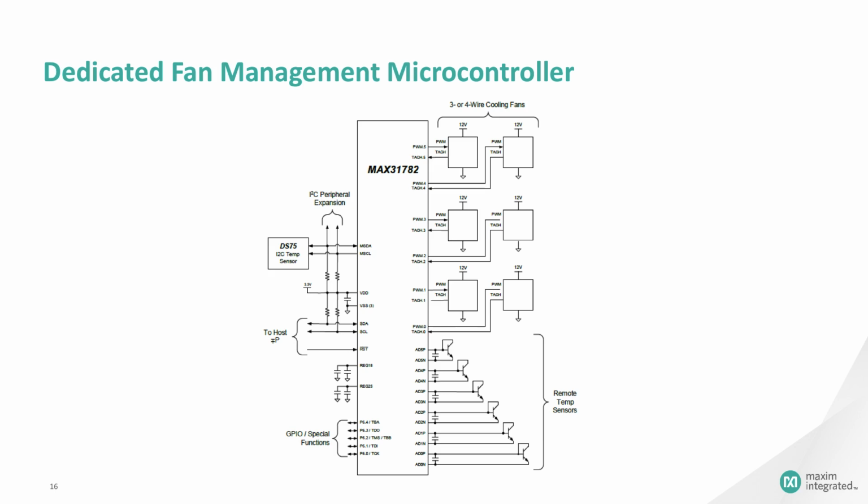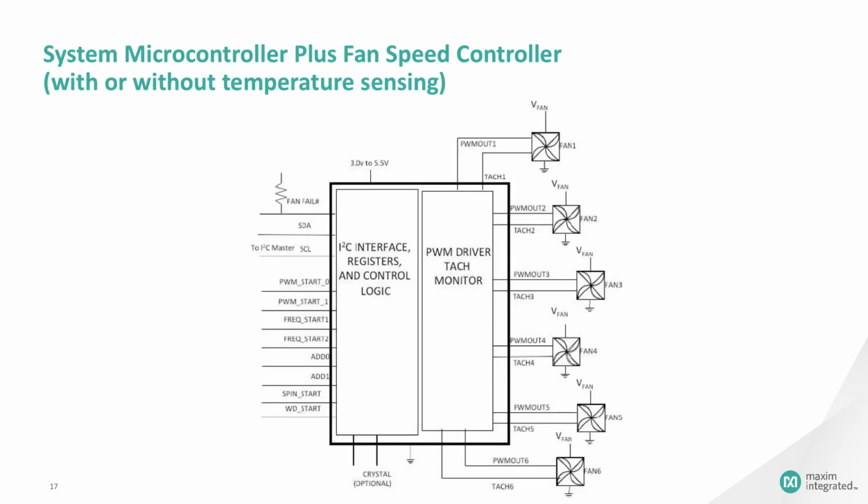System management microcontrollers also include facilities for monitoring, sequencing, and margining power supplies. In some cases, the system management microcontroller will also include black box recorder style fault logging in non-volatile memory for root cause analysis and design improvement.